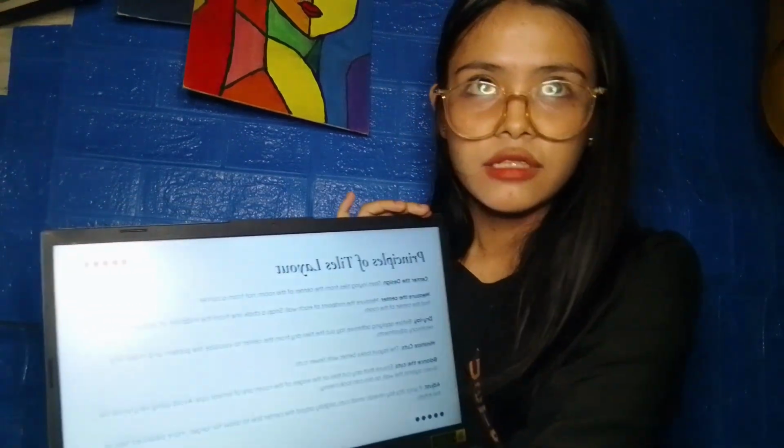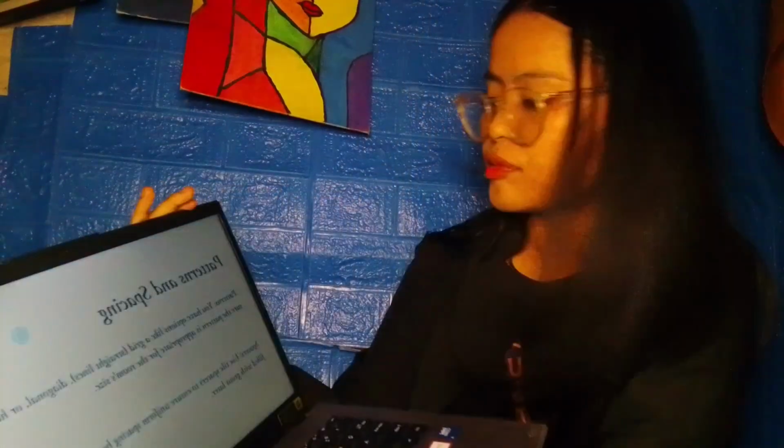The third one is dry lay. Dry lay is done before applying adhesive. It is very effective because you lay out the tiles dry from the center to visualize the pattern and make any necessary adjustments. So before the adhesive, you can still adjust, no?